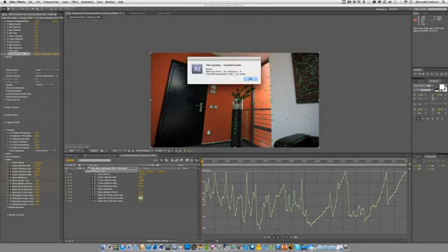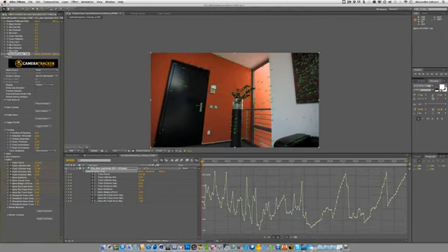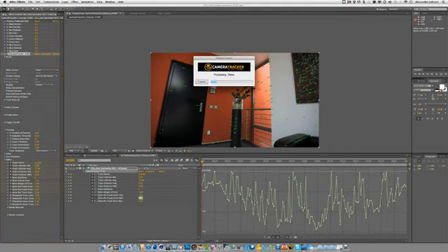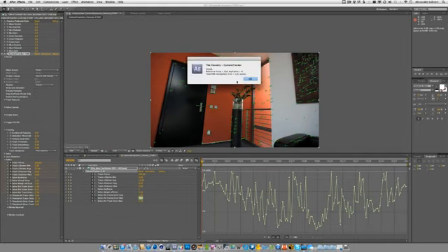Okay, so as you can see we got down from almost 1.7 to 1.3. That's quite good, but we're not already there, so let's just go and pump that down to 5, delete the rejected and the unsolved, and then let's hit solve again. Okay, so after that we just got down to 1.01 pixels. That's quite good for this tutorial.